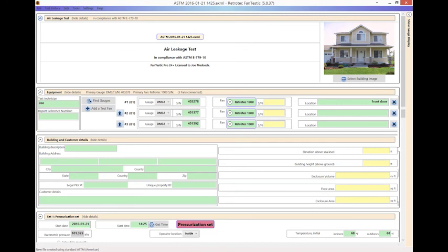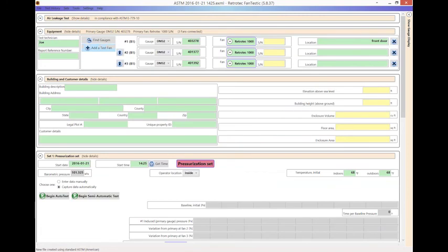Now we can open up the next section, which is the gauges. I have 3 gauges in my office right now that I have set up, and I'll go through the wiring options. You can use USB or you can use Ethernet. We don't recommend you use Wi-Fi. You can, but Wi-Fi can have little glitches that you don't notice, and your data may be paused, or you may not be connected to the gauge, even though we always think of Wi-Fi as being a constant connection.